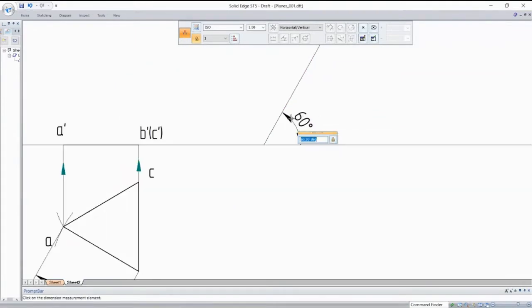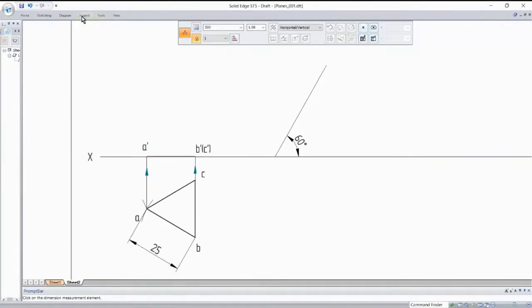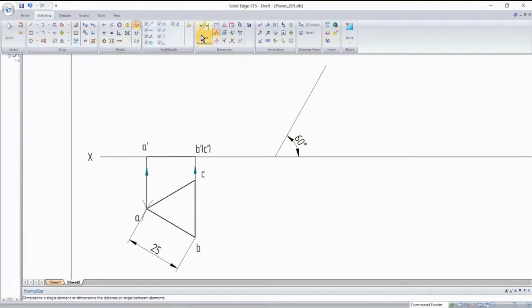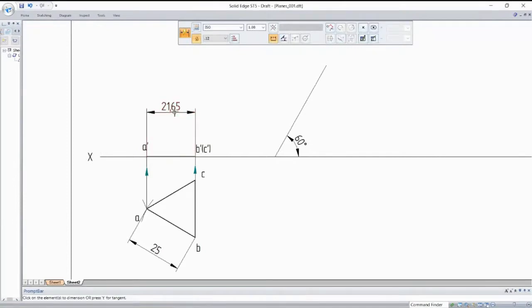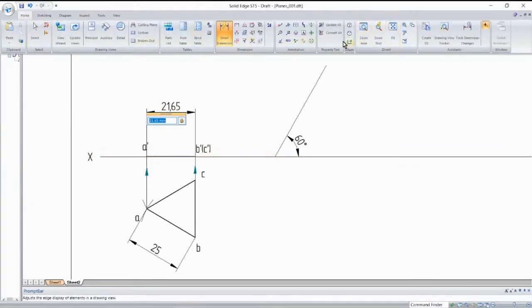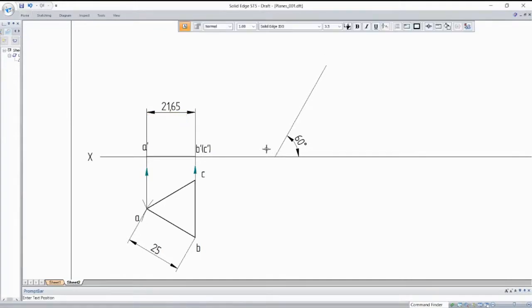And while showing the arrow marks for the angle, you're supposed to follow the protocol of arrowhead 1:3 or 3:1. Now, use your compass. You have to measure this distance. This is how much? 21.65. You use your compass, measure this distance. Before you measure the distance, first let me name this point. If I tilt it, it will be resting on which point? It will be resting on point A dash. So let me write here A dash.